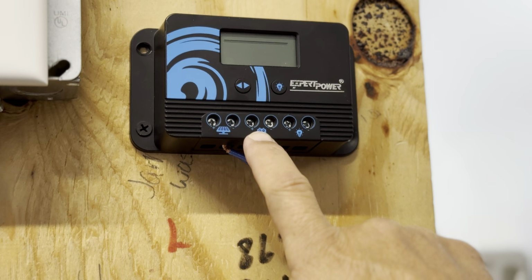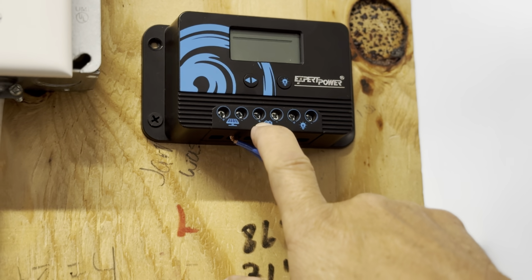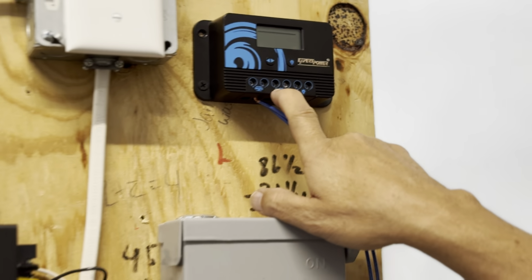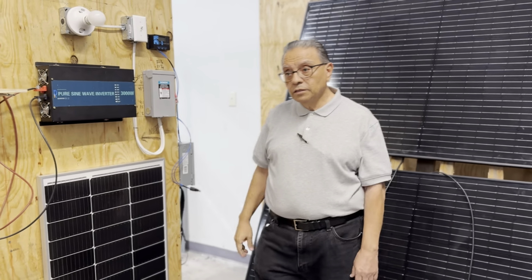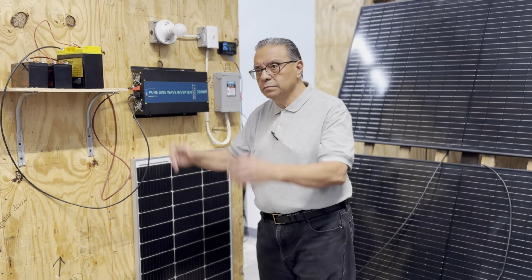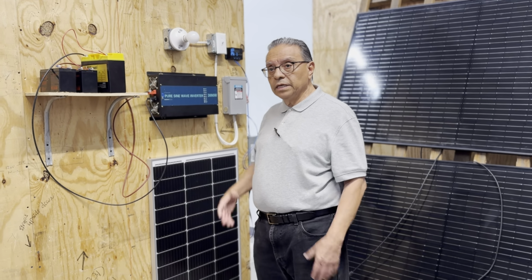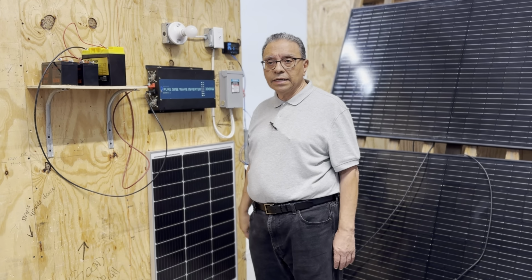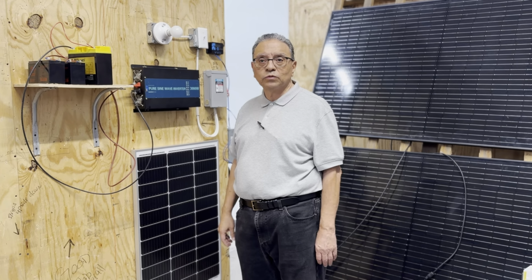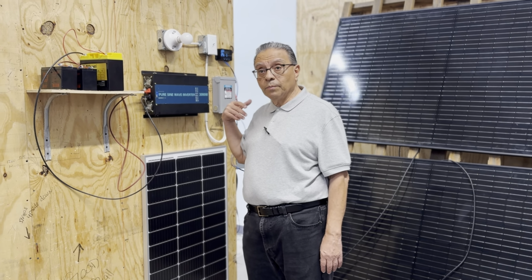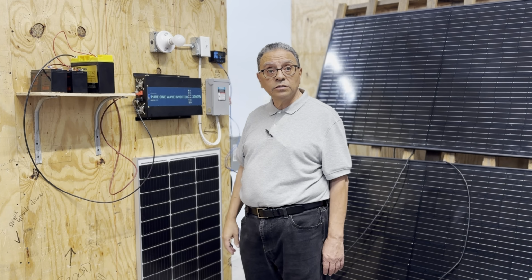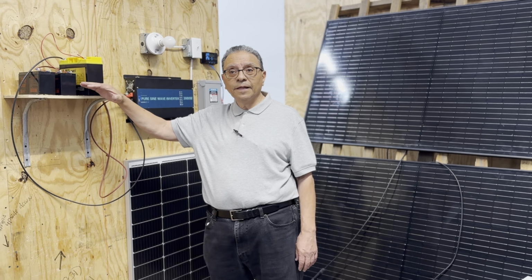To do this, I will avoid overcharging the batteries, and if I overcharge the battery, it will explode. Most probably a bank like this one will be charging 1-2 hours. For the rest of the hours, the solar panel will continue producing energy, but it won't affect this.